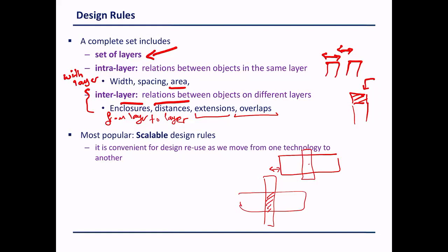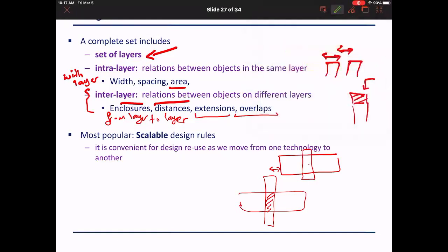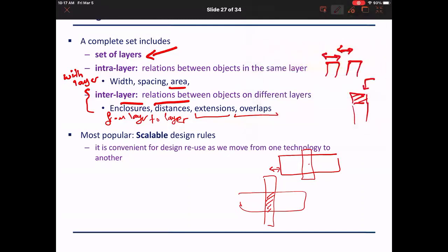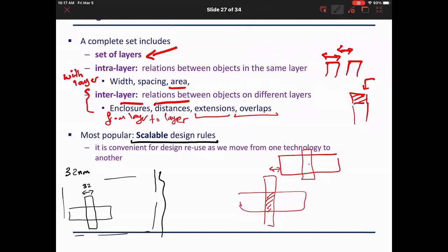Now, what matters for us in all of this, at a high level, is that there is something called transistor scalable design rules. What do I mean? I have a processor, a company like IBM or Intel is investing in designing a 32 nanometer processor. They built, for example, the inverter, and the inverter had L equal 32. And it has all these other gates, and the chip has millions of transistors, and now they want to move down to 24 nanometer. Should they redesign the whole rules?